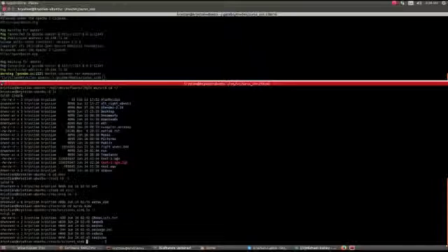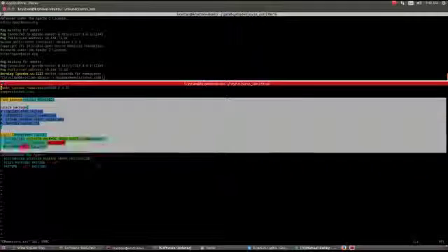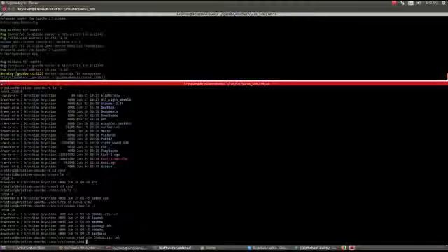So now that we're here, I already put in the CMake list and the package.xml, so we will just take a brief look into the CMake list. And here what we will do is basically just specify the project name, which is actually going to be the name of the package here, that's going to be in our Catkin workspace, and then pretty much you just need the rest of this stuff here for it to be identified as a Catkin package.